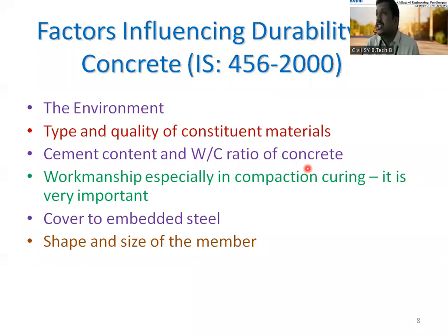Next part of our discussion is the factors which are influencing the durability of the concrete as per IS 456-2000. Which factors are influencing the durability? Now you have understood what durability is. First is the environment. Second, the type and quality of the constituent materials. Next factor, cement content and water cement ratio of the concrete. Workmanship, especially in compacting the concrete, where it is very important to compact the concrete.